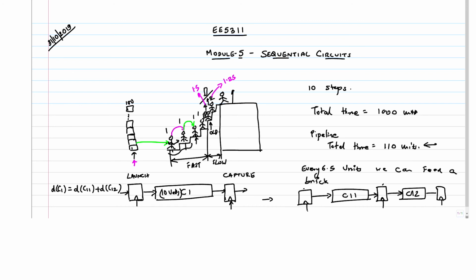So therefore, if I have a clock period like this, if I have a clock like this, right, then what happens? My data should be ready in each clock period, and the delay should be such that data is stable before the next clock edge arrives, right?